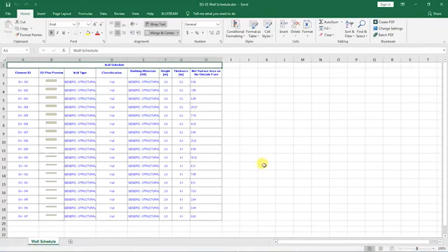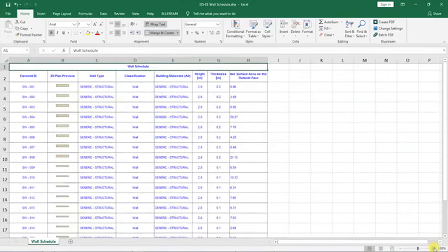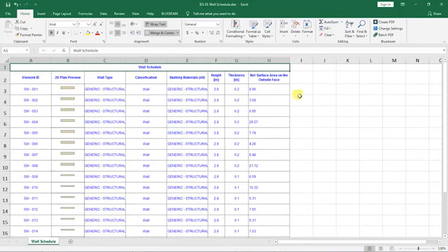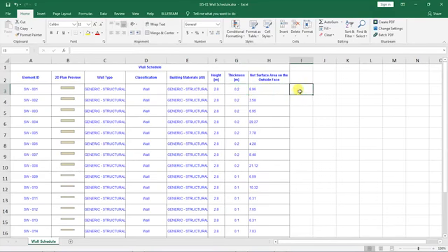So after opening, you can see this is the data that we had in Archicad. I know that if I know the thickness of my wall, the material that I am using to build the wall, and the surface area of that wall, I can apply a cost per square meter to that wall, then come up with a total cost for that wall.